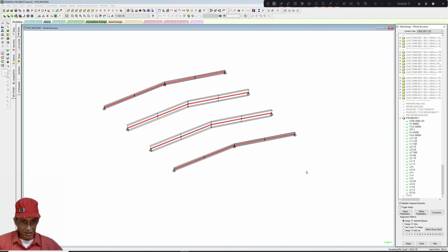Usually STAAD treats the explicit value given to a beam or column as the effective length which has been defined later. So even if we have left LX and LY as 3.125 at an earlier point for some members, if for these members LX and LY have been defined as 1.5 at a later stage, STAAD will treat LX and LY as 1.5, not 3.125.